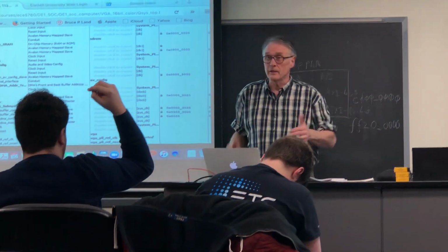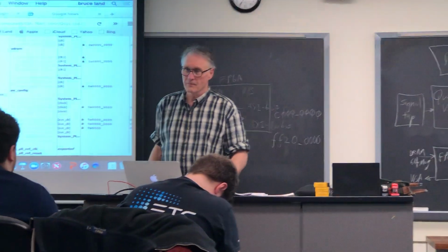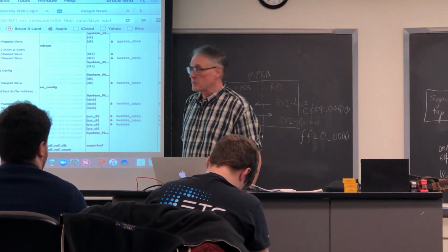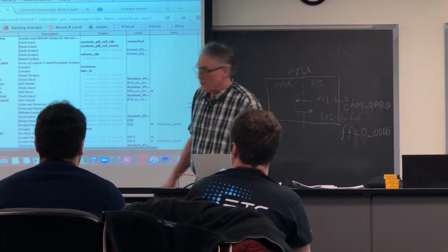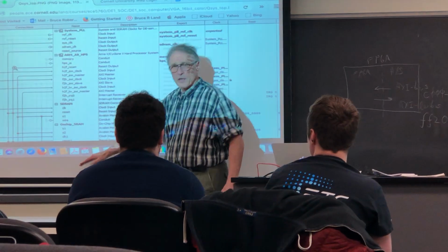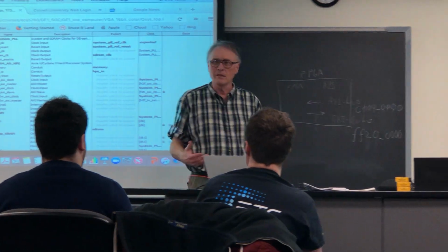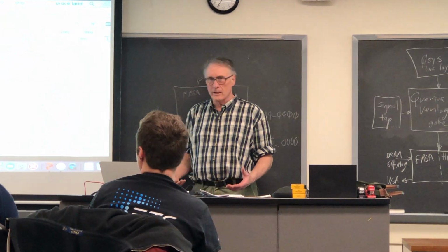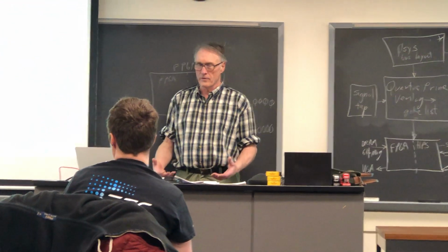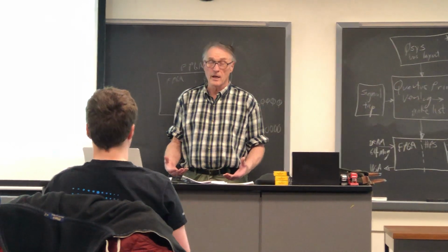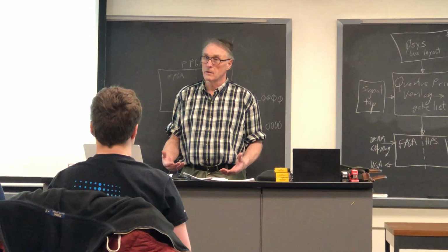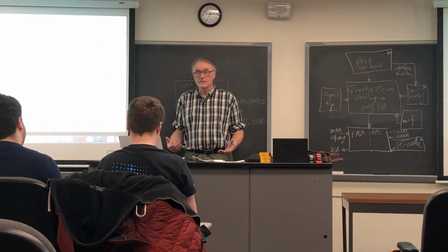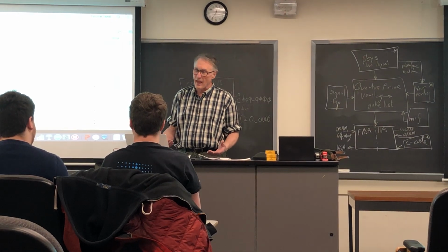It's maddening. It's so complicated. Yes? Okay, so when I first open up the Qsys graphical interface, what is it going to look like? How much of this stuff is already going to be populated? If you start with a new project and open Qsys, all you will see is a clock, nothing else. Nobody in their right mind does that, right? This system is so complicated that you're going to start with a project which works and modify it. So we're going to download the files to your VGA project, and it already is all set up. Absolutely. Otherwise, you won't finish setting up Qsys before the end of the first lab.